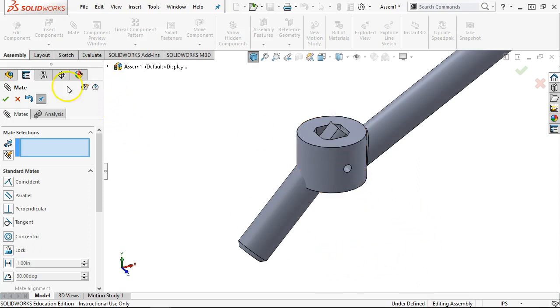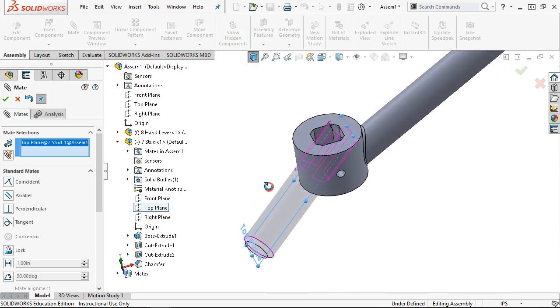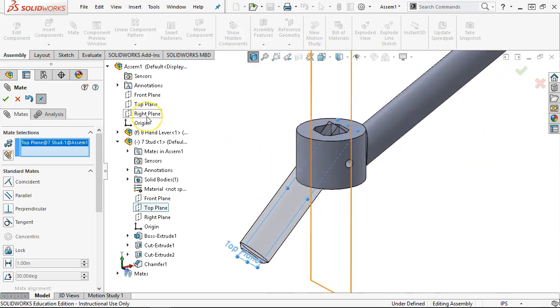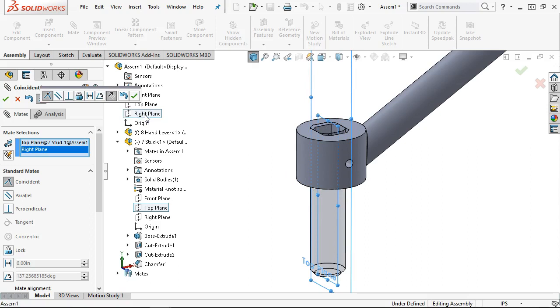All right, so we went to the concentricity first. My next selection would be, let's expand out. So the little flyout goes to the assembly. I can see the instances of those parts, and I would like, that looks like the, nope, maybe, top plane would be okay. The top plane and the right plane to be coincident. Well, not exactly coincident. All right, well, this is one of those cases where if I needed to change this, if I needed to update its location, I really don't want my geometry to error out on me.